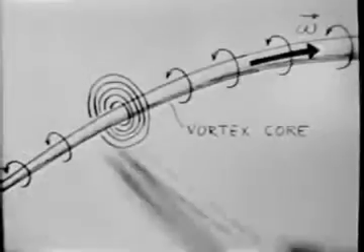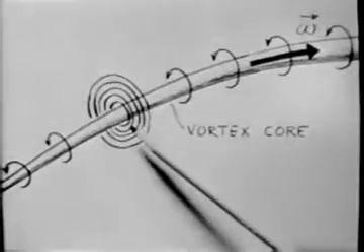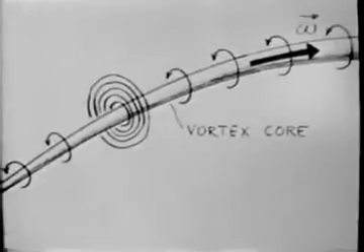Sometimes the vorticity is everywhere in the fluid, distributed throughout. But often the vorticity is very large in a thin thread of fluid, while the remaining fluid is without vorticity. Then we can simplify our thinking by lumping all the vorticity into a concentrated vortex core around which the fluid spins, and then by pretending that the remaining fluid is entirely free of vorticity. The vorticity is infinite in the core, because a finite amount of vorticity has been dumped into zero cross-sectional area.